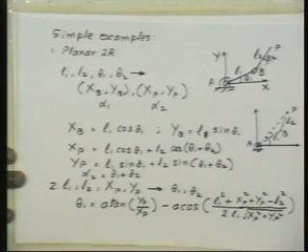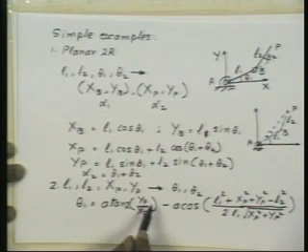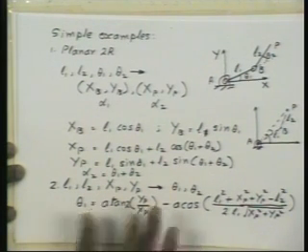The other thing which should be noted is that this angle, A tan inverse, is normally known to within 2 quadrants. You don't know exactly which quadrant it is if you use A tan. But we know exactly what yp and xp are, and so where this particular point P is, in which quadrant it is. So we can precisely calculate this angle, including the quadrant, and there is a function which gives you that, which takes 2 arguments. It is called A tan 2 in most of the languages, and you give 2 arguments, yp first and xp next. So if you use A tan 2, you get this uniquely. Otherwise, you get 2 solutions for that.